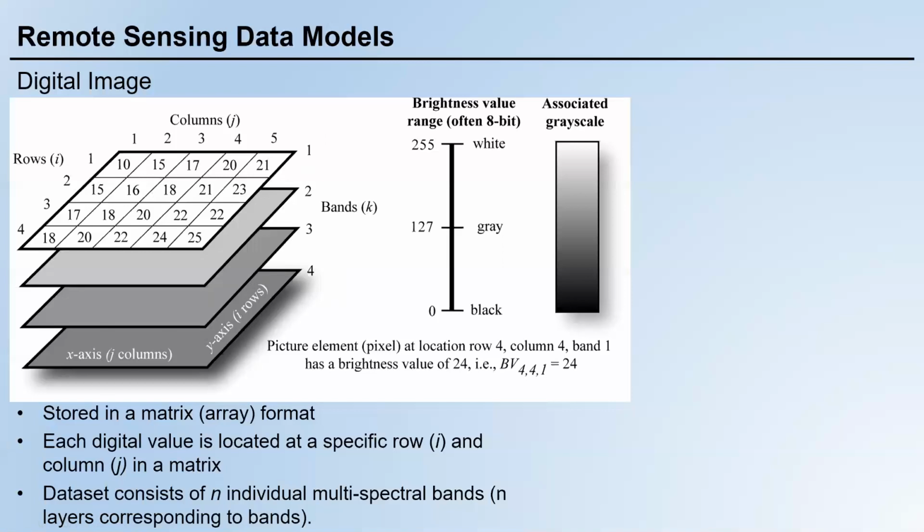So when we're talking about remote sensing imagery, the first question you should ask is, what is the band I'm looking at? Because a sensor could have multiple bands. Even for the same sensor, even for the same area detected by that sensor, different bands could have different reflected energy, even for the same pixel. The concept of band here is pretty important.